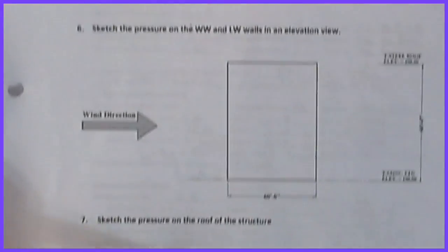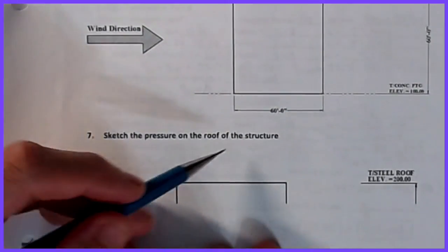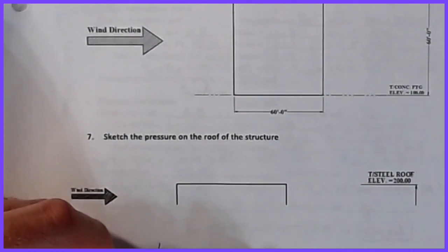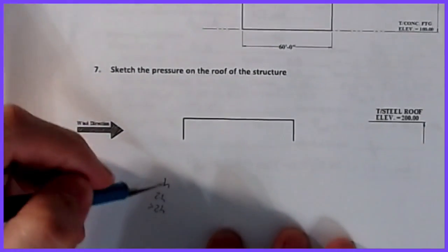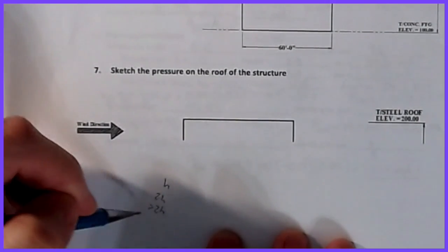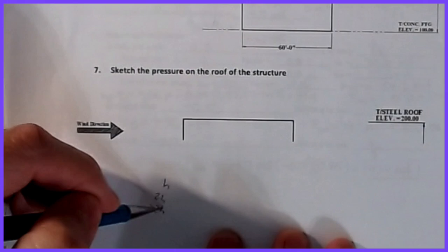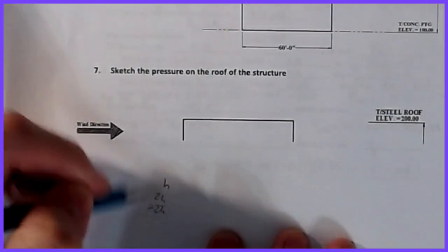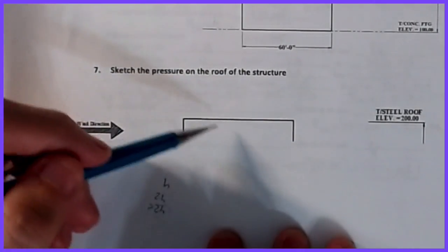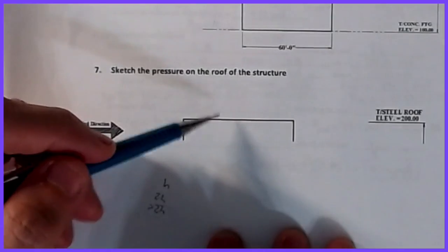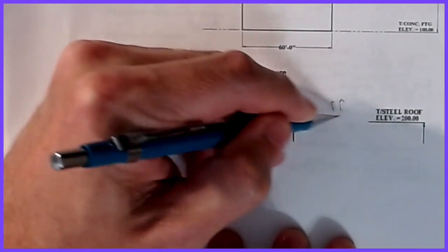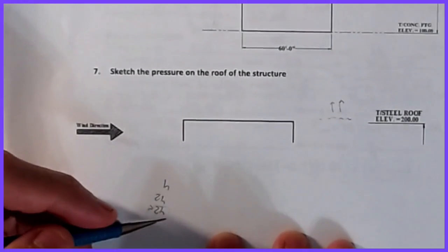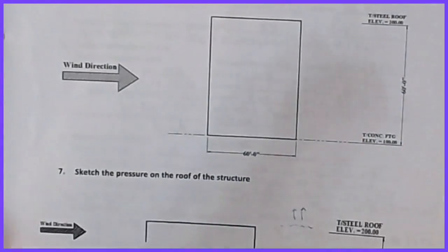The roof is a little bit different. Okay, it could be 3 regions, but remember we had H, 2H, and then greater than 2H is our distance, right? So this is region 1, this is region 2, this is region 3. For a small roof, it's possible that maybe this guy isn't even on the roof anymore. And if that's not the case, then you could end up with just 2 regions, which I think this building will only have 2 regions on it. Okay, and that's fine. You just draw what it's capable of supporting, because I can't have wind out here somewhere pulling up because there's nothing for it to pull up on, right? So we draw all 3 to scale, and then whatever's on the building is what's on the building, is the way that we would start to handle that.